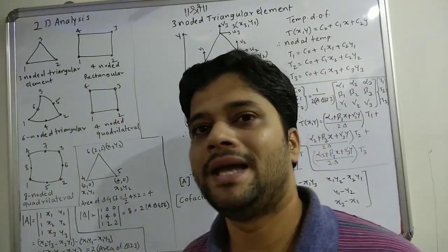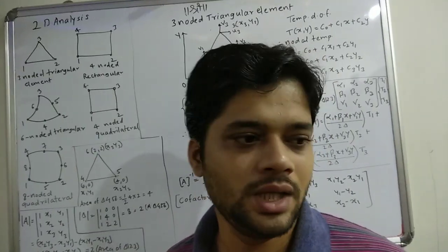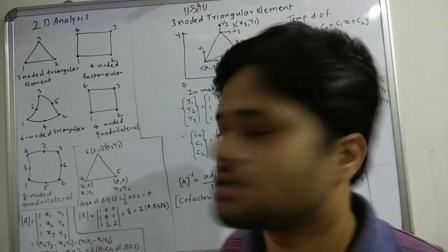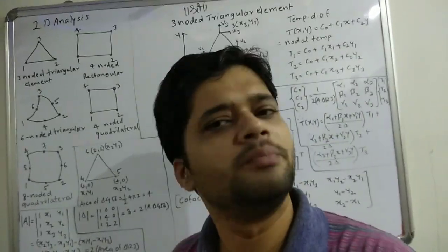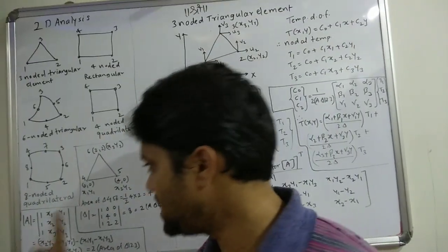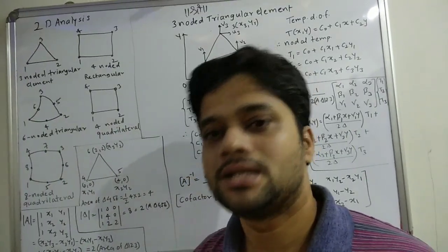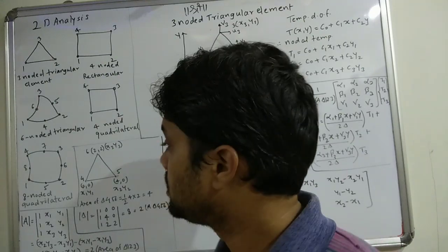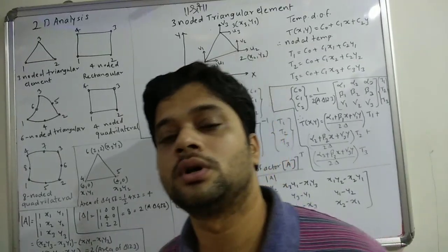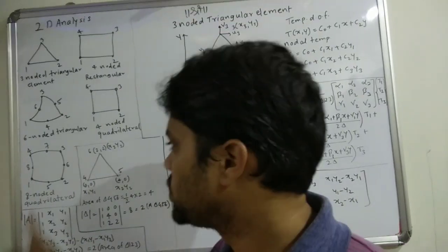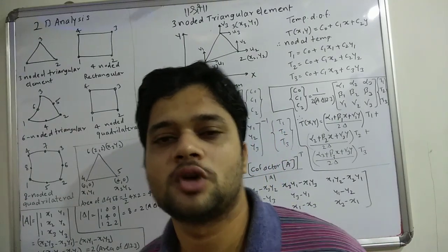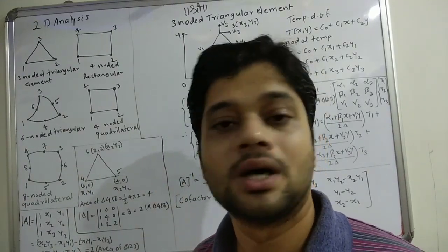So the edge phenomena will be linear, so I can have slanted edges and I can achieve many shapes. But when I add extra nodes, it becomes an 8-noded quadrilateral element. The nature on each edge becomes quadratic, and that gives us many more different shapes. That allows us to use this element again at intricate shape geometries where I have curvatures involved.